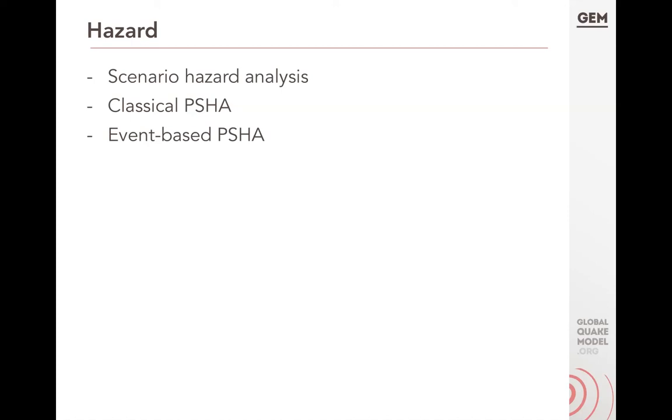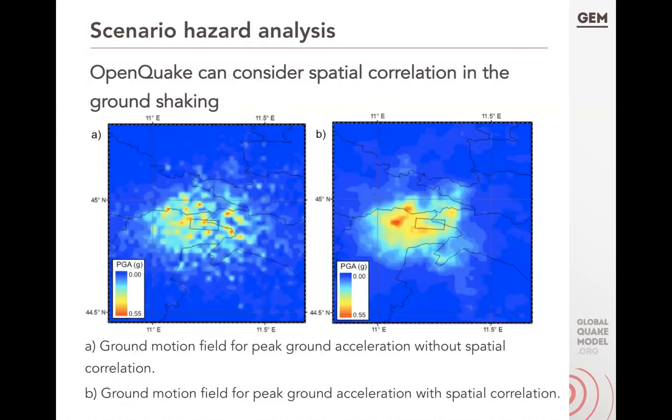And so for each of these earthquake events that are simulated in your earthquake catalog, you can compute ground shaking maps and then come up with statistical ways to estimate your seismic hazard curves or seismic hazard maps or the uniform hazard spectra. So we'll talk a bit more about this in tomorrow's session on the probabilistic hazard and risk analysis.